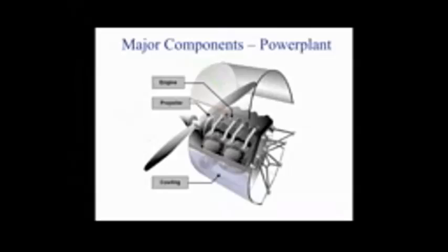A propeller is a rotating airfoil that produces thrust through aerodynamic action. A low-pressure area is formed at the back of the propeller's airfoil, and high pressure is produced at the face of the propeller, similar to the way lift is generated by an airfoil used as a lifting surface or wing. This pressure differential pulls air through the propeller, which in turn pulls the airplane forward.